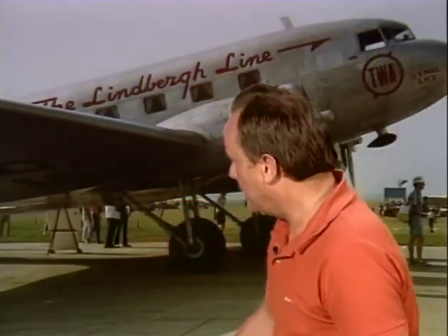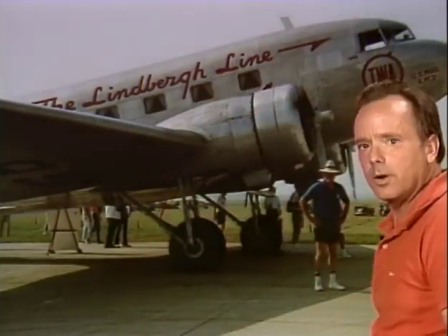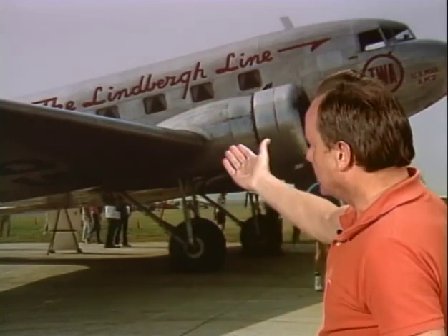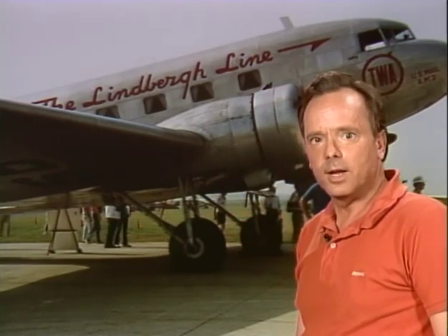Now let's talk about cable tension. Sometimes big aircraft like a DC-3 or a Constellation have a tension regulator in the flight control cable system. That's generally used in a large all-metal aircraft, primarily to retain a set tension on the cable. So you might have a tension regulator in this airplane if you were flying a DC-3 or a Constellation.